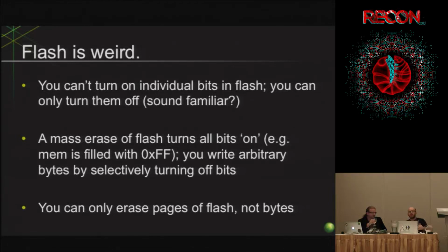On other architectures, it can be useful because sometimes the way they're organized, you'll have pointers up at the top that you can turn bits off and make the value jump lower, and then maybe you can modify things that are down below. I can't remember which architecture it is, but one of them allows you to modify the data down below where it has a lower address space, and the one that has a higher address space is read-only Flash. But you can flip those bits off, and then it'll allow you to jump down into the lower areas. But we were the reverse.